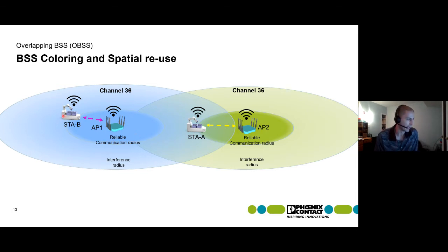So again, depending on how frequent communication is here and how much other stuff is happening on this access point, if there's a lot of communication happening really quickly, it is possible that this station will not gain access to the RF spectrum, the air, to send its data for a quote unquote long period of time. And a long period of time could be 100, 200 milliseconds. But for an industrial application that's time sensitive, that's a really long time.